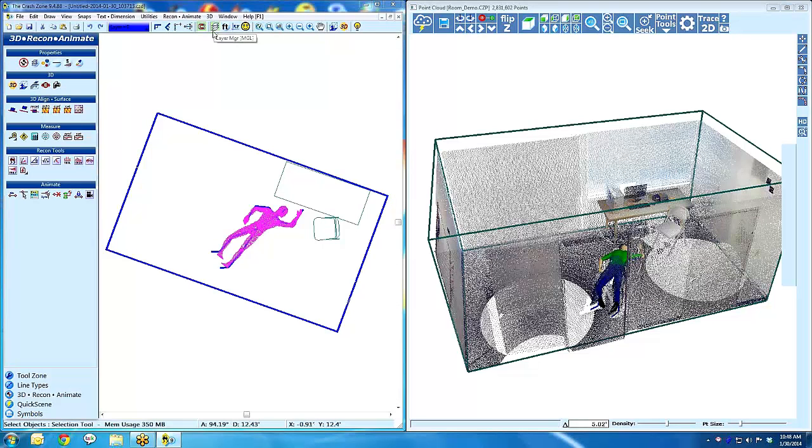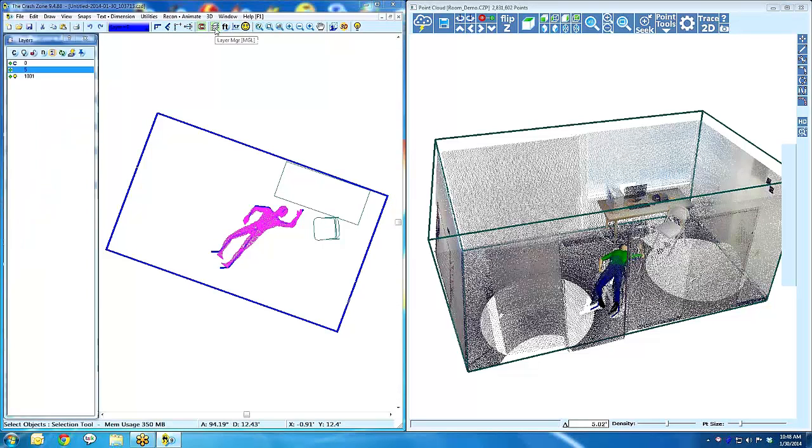You can name those layers as well so you can remember what they are. I could click on 8, name it body, hit OK, and for 5, hit the little N for name and call it cone. Then we can turn them back on or off, or hide the body like that.